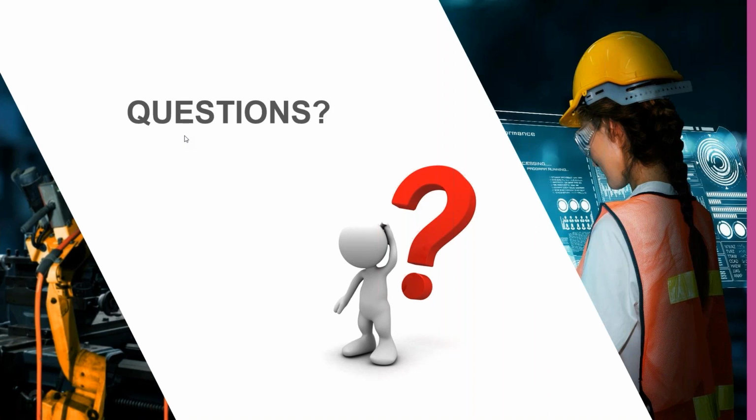Typically, Word is not used for building the guides. We have what's called Arbor Text Editor, which maintains the PVZ link. So if you were to change the size of one of those parts, like a dimension in Creo Parametric, and you resaved it as a PVZ file over the original, it would update inside of Creo Illustrate.